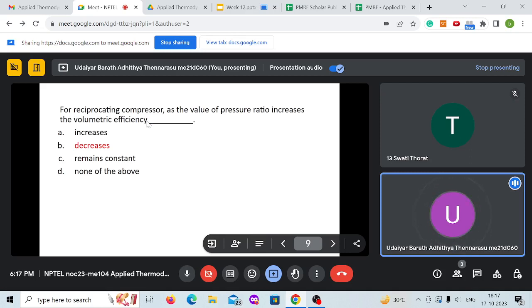When the piston moves down, the pressurized fluid inside the compressor will take a larger volume of the suction stroke to reach the suction pressure. So you will have very small volume left to take in new fluid.